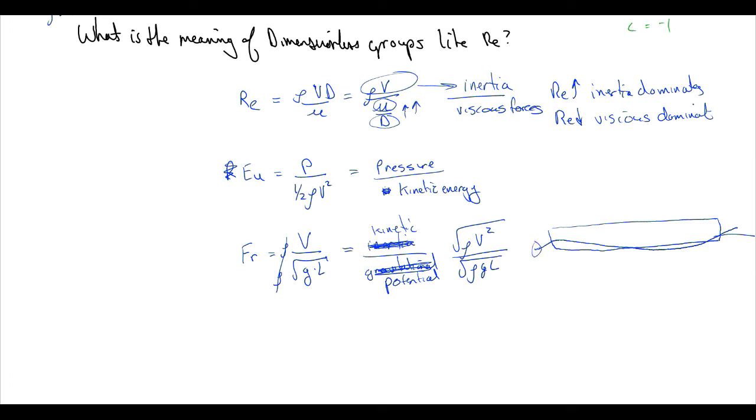And it turns out that the longer a ship is, the longer this wave has to be in order for that ship to have to overcome it, so the ship can go faster, right? Which is one of the reasons why ships keep getting longer and longer so that they can go faster and faster more efficiently. Also, by the way, that little bow bulb was an innovation to try to reduce the bow wave, and it actually does a decent job of it. But it's still fundamentally there. It just moves the limit as opposed to eliminating it.